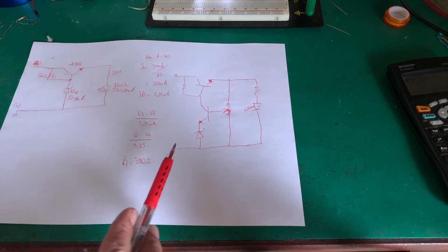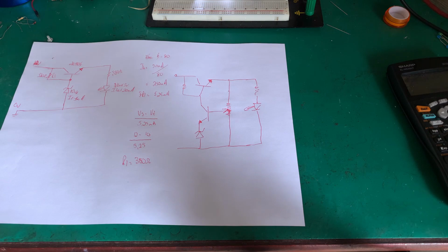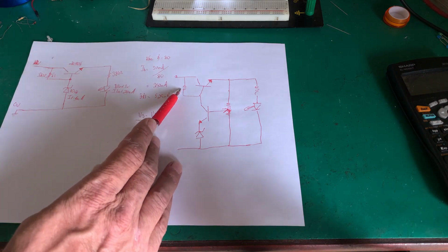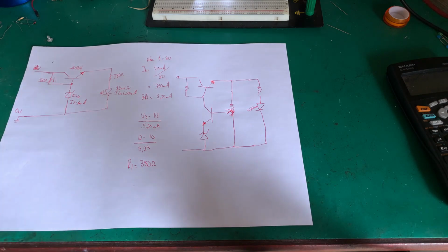This will give you better control over your voltage, less power dissipation and things like that. It's a better efficiency. The calculation for calculating that resistor is exactly the same as what we did for the LED. This pot, I'm just putting a 1K 1 turn in, nothing fancy. The Zener will stay the same, so the same things apply.